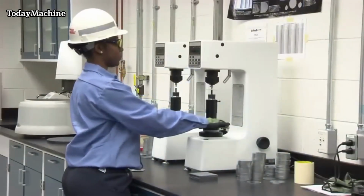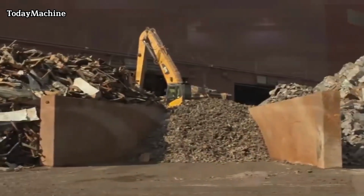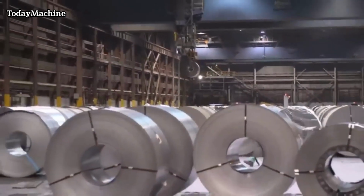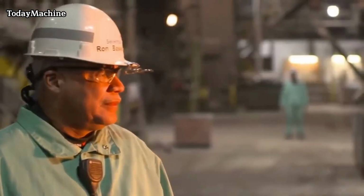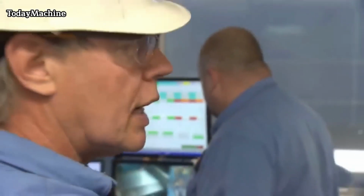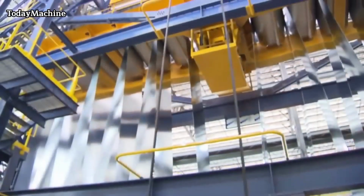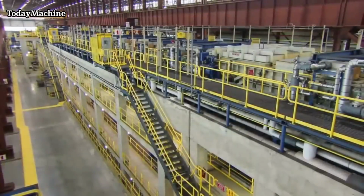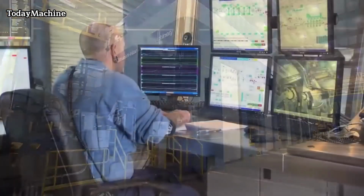After immersion, excess zinc is removed from the steel by employing air knives or other mechanical means. This step helps achieve a uniform coating thickness and removes any excess zinc that may cause drips or unevenness on the galvanized surface. Following the removal of excess zinc, the steel is cooled in a quench tank or by air cooling. This rapid cooling solidifies the zinc coating, ensuring its adherence to the steel surface. Proper cooling is crucial to achieve a durable and uniform coating.